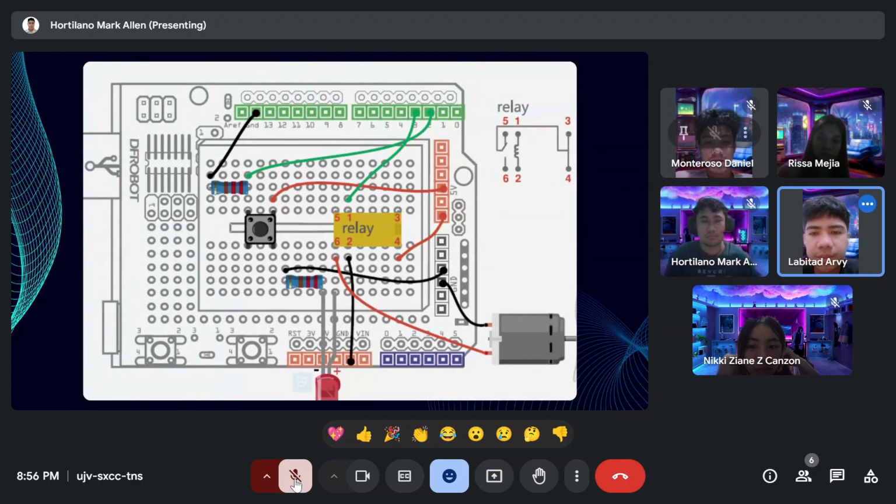The relay has 6 pins. Pin 1 and 2 on the relay are input signals and are separately connected to digital pin 3 and GND on the Arduino. Pin 3, 4, 5 and 6 on the relay are the output signals, but we will only use pin 4 and pin 6 at this time. A relay is similar to a push button, which has 2 connections as well.